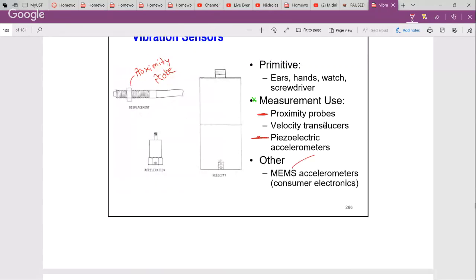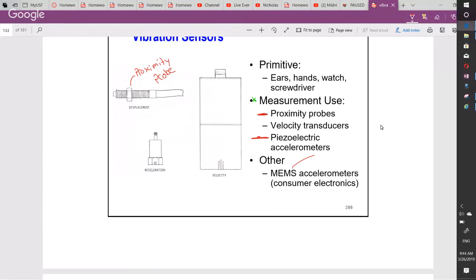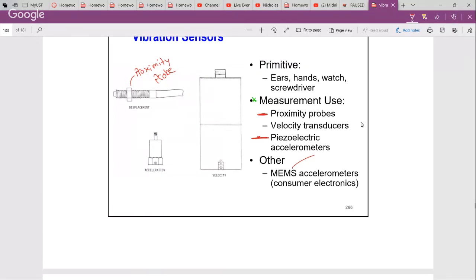In the world of consumer or modern electronics, the word accelerometer is a little bit misused from a vibration expert perspective. Sensing G, a gravitational constant, is hardly the same as measuring or sensing acceleration from a range of a micro G to 1,000 G's amplitude, and from 1 hertz to 4,000 hertz.